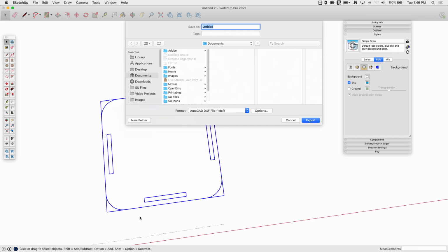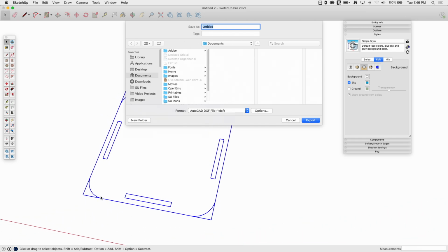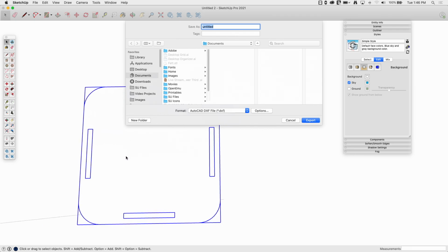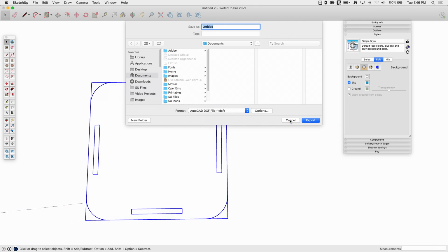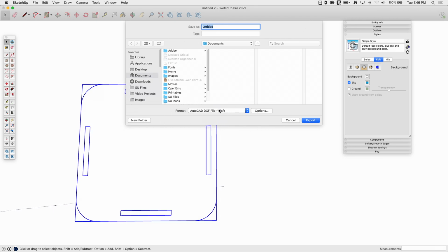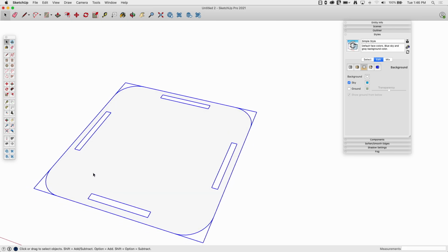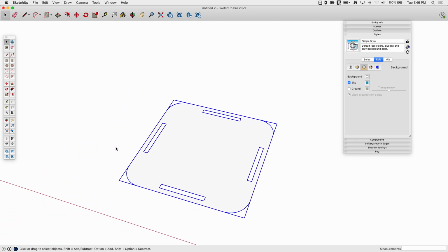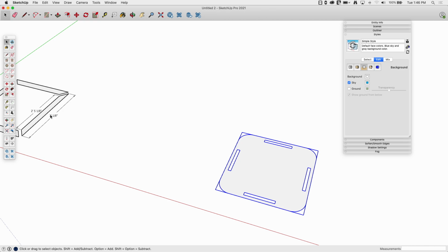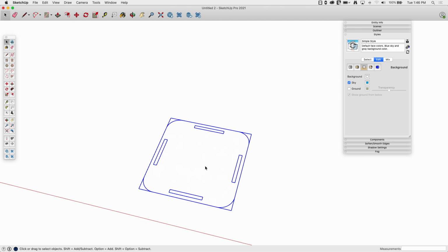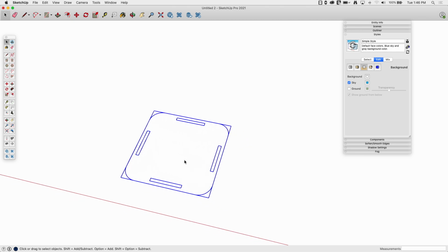By exporting as 3D, we did a whole video on this, it is going to export these curves as true curves rather than segmented lines. But that's what I would do to export for CNC. I would do it directly here from SketchUp using a DXF file, 3D export. So that is probably the other 2D thing that I would export. That would be something like I said, a screenshot PNG or data to go to CAD/CAM software for CNC.